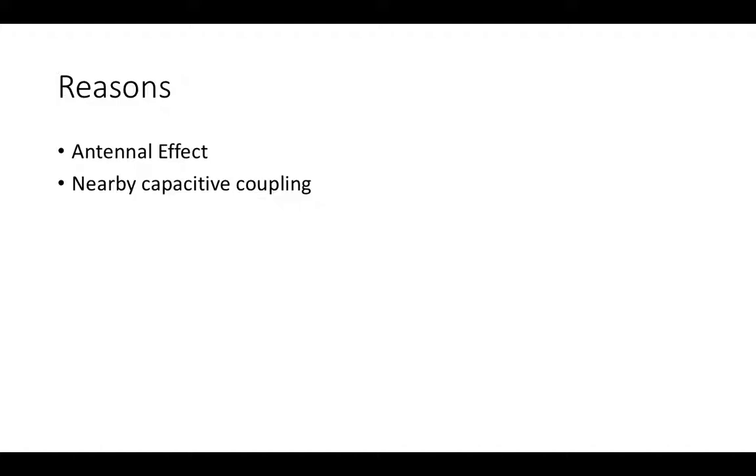And in the latter case, we call it nearby capacitive coupling. That is, there might be a neighboring pin that has a certain voltage, such that the air medium acts as the dielectric and influences the value of the A0 pin of the ADC.